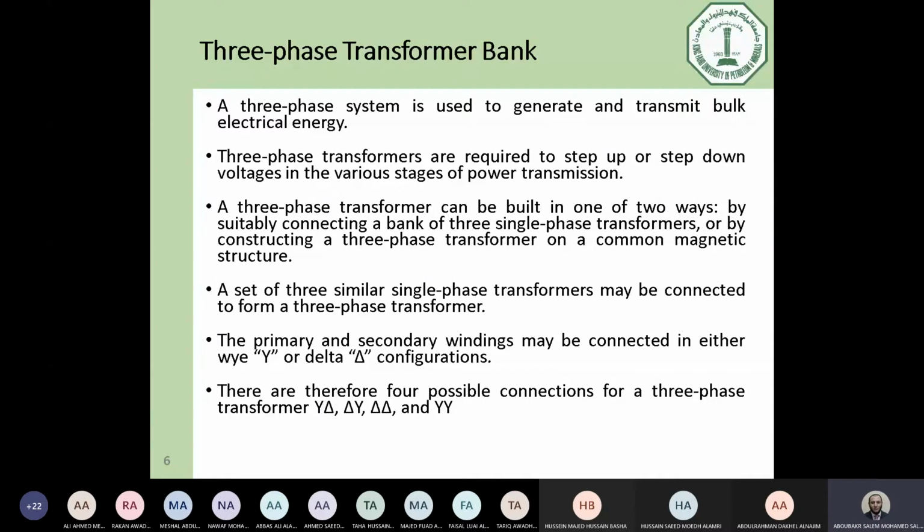However, if you have a central air conditioner, for instance, a machine of 10 kVA, in this case you cannot take single-phase 10 kVA from your home, and it's not safe for the wiring inside your home.